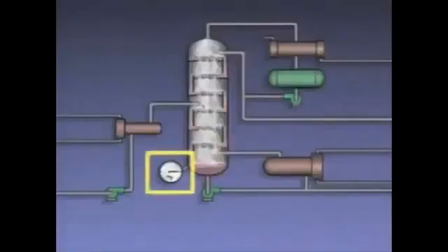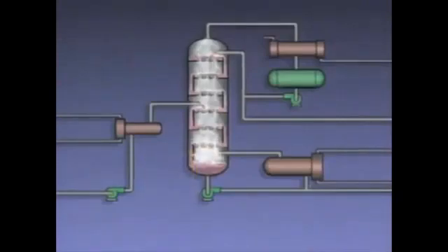One of the most common causes of excessive vapor flow is too high a temperature in the bottom of the column. If the temperature in the bottom of the column is too high, too much liquid is vaporized, and the vapor flow rate up the column increases. The increased vapor flow forces liquid up the column, flooding trays in an upward progression.